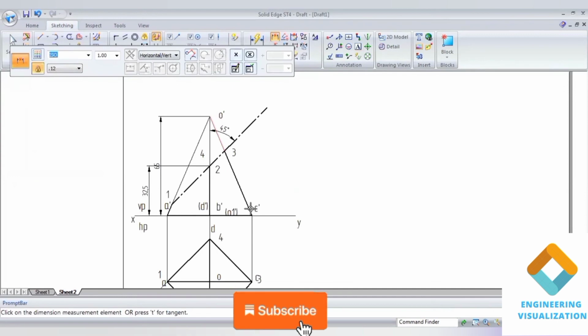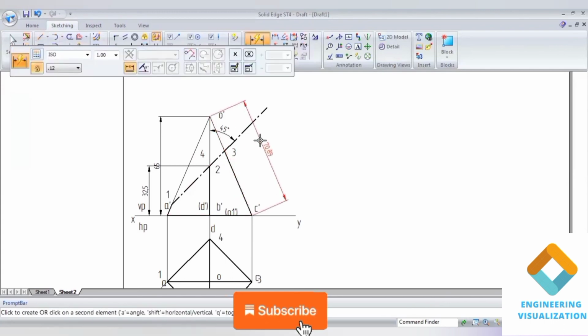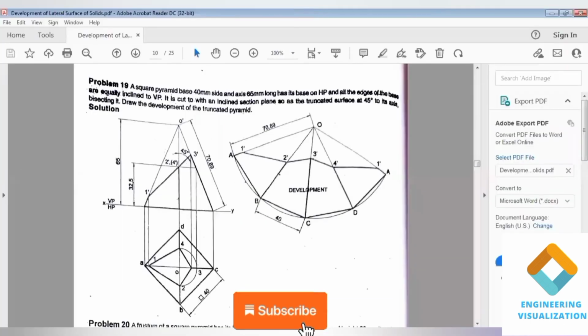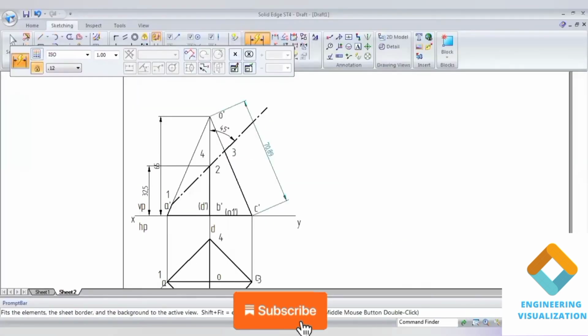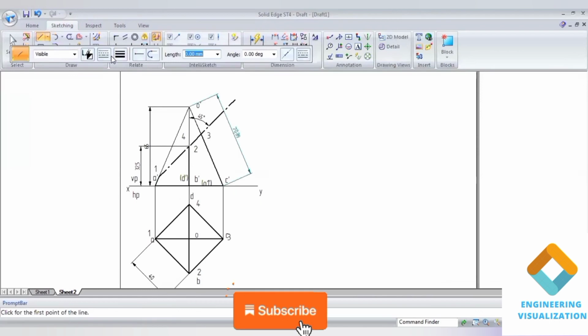Then measure the slant edge dimension. Here you need to find the slant edge dimension using two points. In the dimension they are showing horizontal and vertical, right? This length also you can take, because that is also a slanted edge length. Just for reference I'm drawing the slanted edge here because I have split it there. Now we are getting the slanted edge length, the same length we got. Using this slanted edge length we will construct the development. For the same length we'll draw a line.